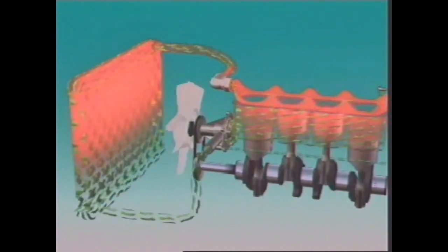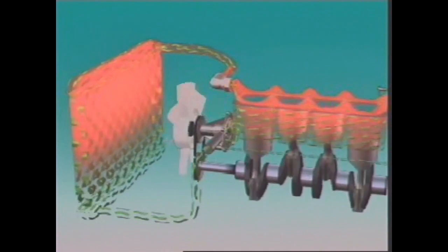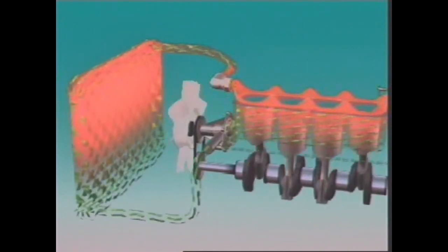Where coolant touches tube walls and where the tubes touch the fins, heat is removed from the coolant by conduction, then by radiation and convection at the surface of the fins. Air rushing by carries the heat away. Liquid emerges cooler at the bottom of the radiator. It travels through the lower radiator hose to the water pump inlet, then through the engine again.